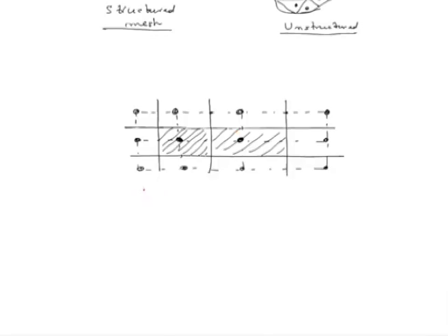So this is our face centered arrangement, and you can clearly see that we can generate such faces which will intersect and lead us to non overlapping finite volumes only if our nodal arrangements were in a structured fashion. So this face centered approach can be utilized only for structured grids. The cell centered approach can be used for both structured as well as unstructured finite volume formulations.